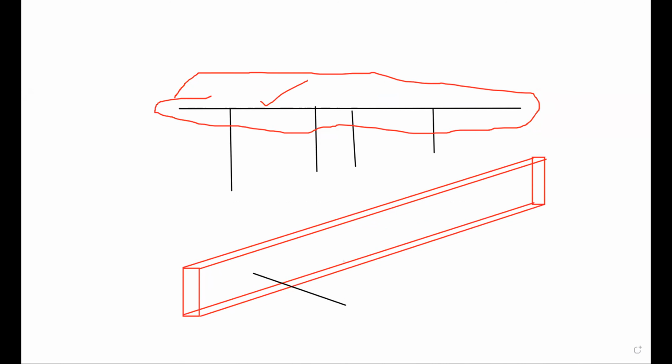In this direction there is one beam, there is another beam over here, and there is another beam over here which is going into the other direction, and there is another beam going like this. So this is actually completely one beam only. So you have to give 3 or 2 rods which will pass common to all the beams. Then at every joint, based on the reinforcement difference, 2 bars, 3 bars extra, 2 bars extra, 3 bars extra, 4 bars extra. The different reinforcement is there.